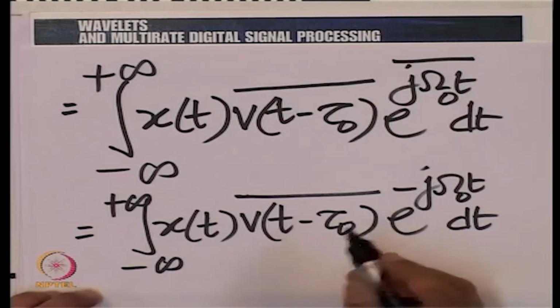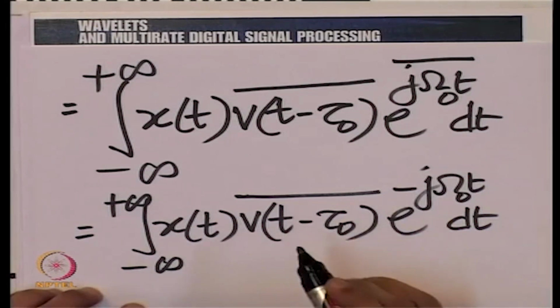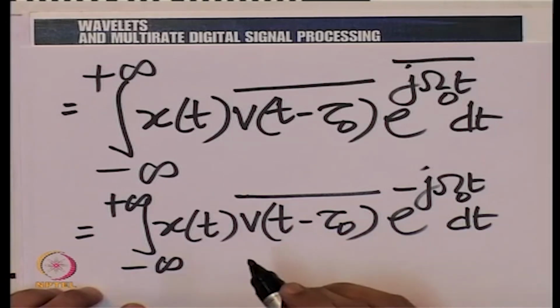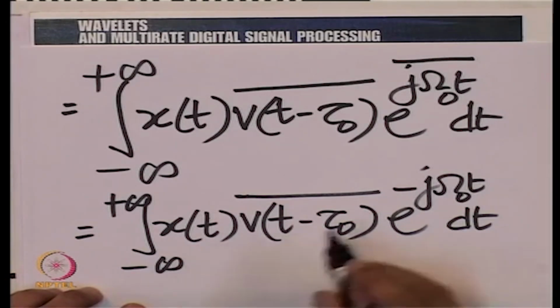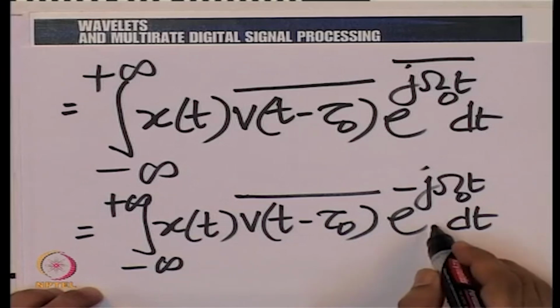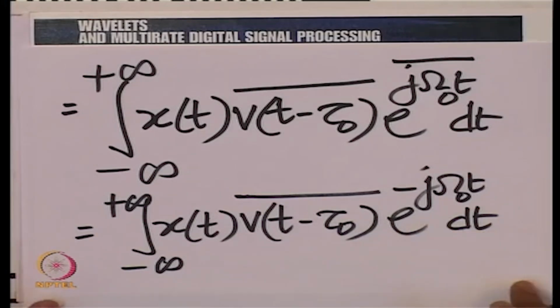In the rectangular function, there is no weighting. In the raised cosine or the triangular or the Gaussian function, there is a weighting, different weights given to different points around tau 0, followed by a Fourier transformation. So, looking at the frequency content in a certain region.